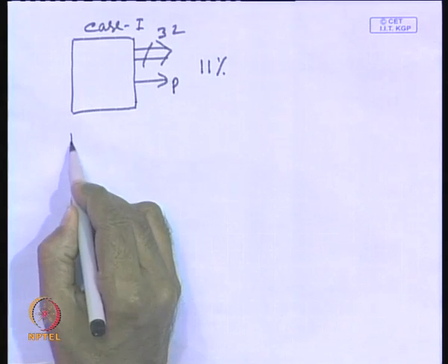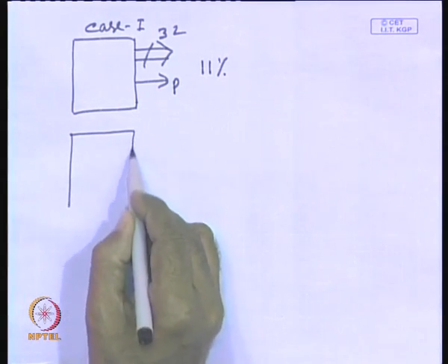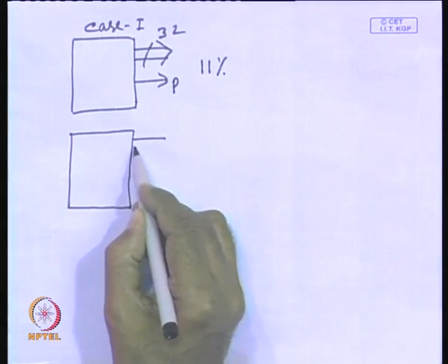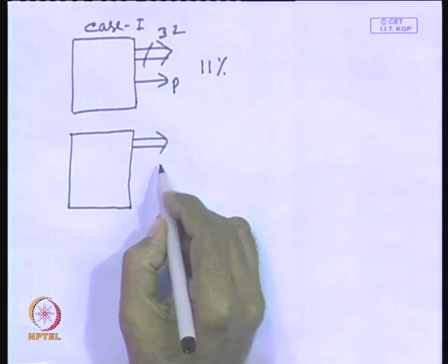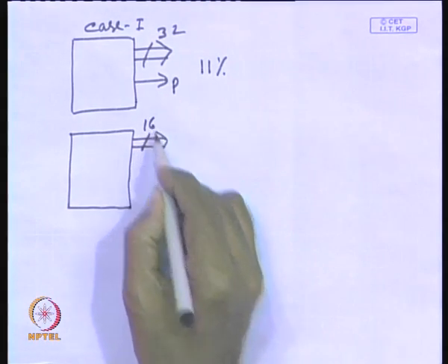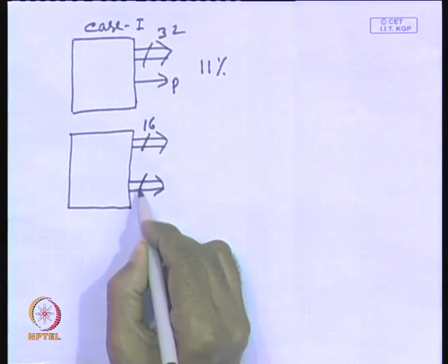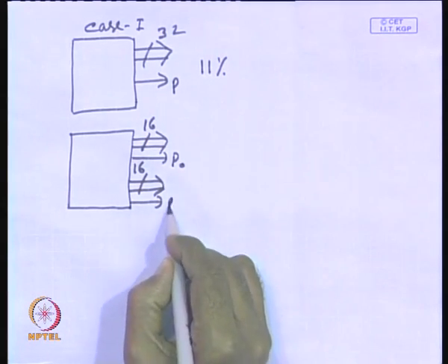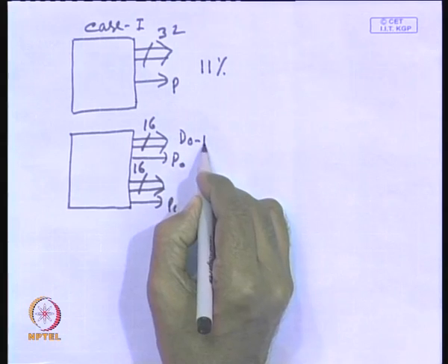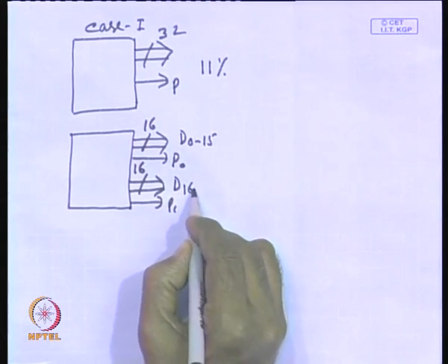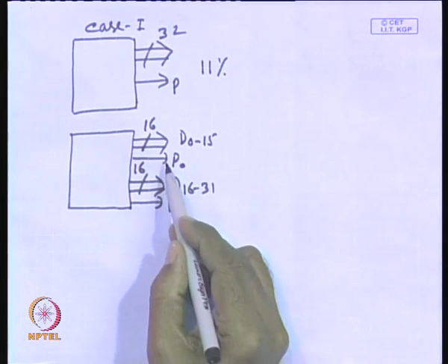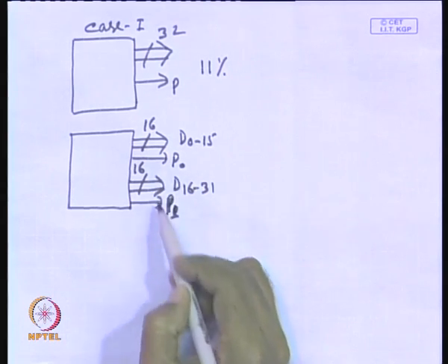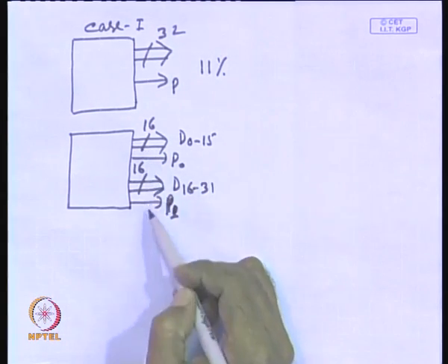Now, you have got several alternatives. You group the bits into two parts. Here you have got 16 and here you have got another 16, and obviously you will require two polarity bits, say P0 and P1. Say it is D0 to 15 and D16 to 31. So, here you have got two additional polarity bits. You are increasing the redundancy by grouping into two parts.